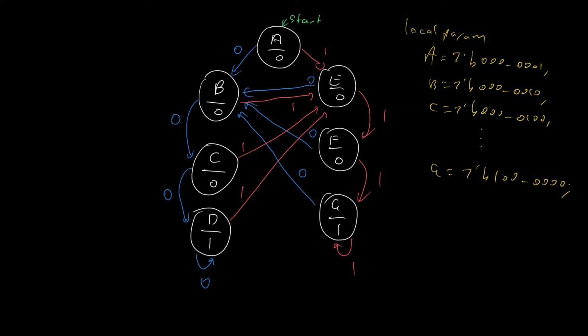This means that the next state logic doesn't have to waste any effort trying to figure out what state it's in. It just simply has to look at which bit is a 1 and it knows what state we're currently in. This means that if we wanted to, we can actually design this finite state machine by hand. We can design the hardware implementation by hand. Now these days we don't really need to know this because Quartus will just do this for us, but nevertheless, to get some insight into how changing the state representation can significantly change the hardware, we're going to look at this now.